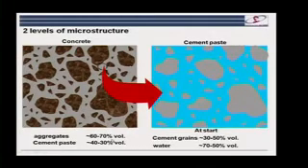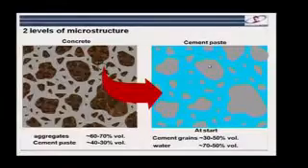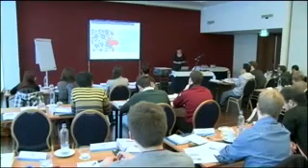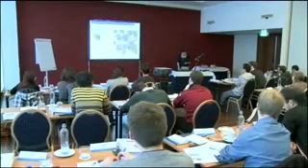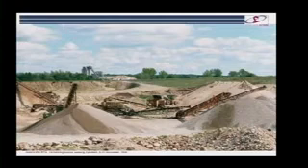And the reason we can have a larger volume of aggregates than we can of cement grains is because we have a larger difference in the size between the small aggregate and the large aggregate. There we can go over 2 or 3 orders of magnitude in size. And as I showed you before, because we have these very different sizes, this means we can increase the solid fraction. And to do that, the technology has been well developed.